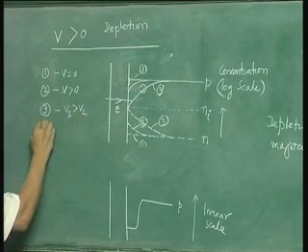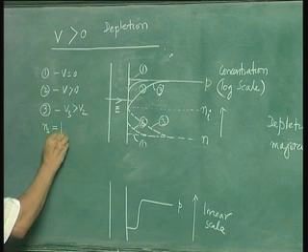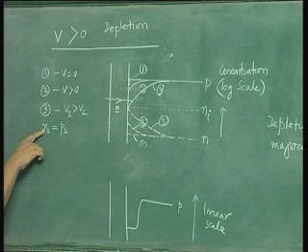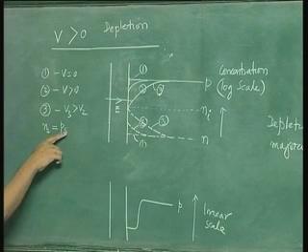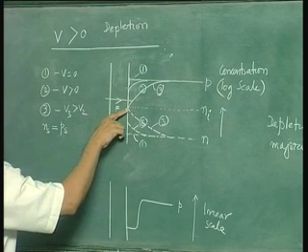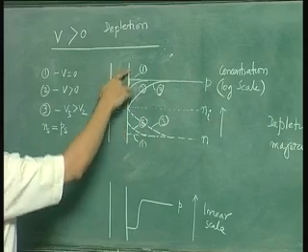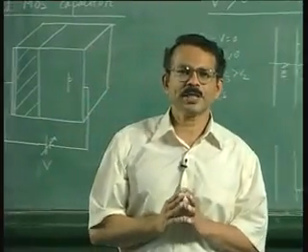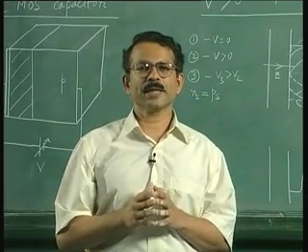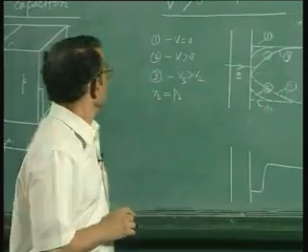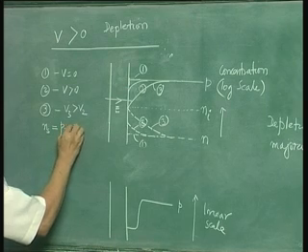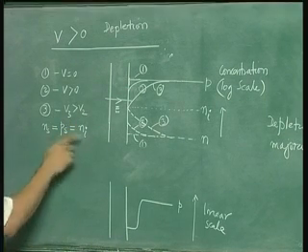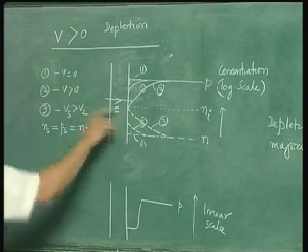The voltage is such that Ns is equal to Ps, that is the surface concentration of electrons is equal to the surface concentration of holes. Surface concentration is the concentration at the interface. The terms interface and surface are used interchangeably in the semiconductor literature. Obviously when Ns is equal to Ps, since there is equilibrium in the semiconductor, both will be equal to Ni.